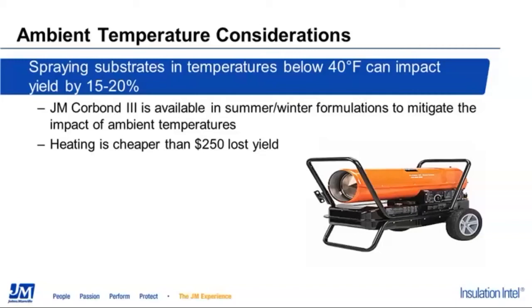So one of the things that we want to look at is, well, what about the options of heating the spray environment? This does two things for us. We're in a happier, better work environment anyway, and then we mitigate that yield loss. So when you look at something like the salamander heater, and that's one way of heating the spray environment, let's just say we run 8 gallons of fuel through that heater in a day, costing us $25, $30, $35, and now we have a happier spray environment. We get better yield on our foam. We don't have that yield loss, and that yield loss could be $250 on the drum set at 15% or whatnot.